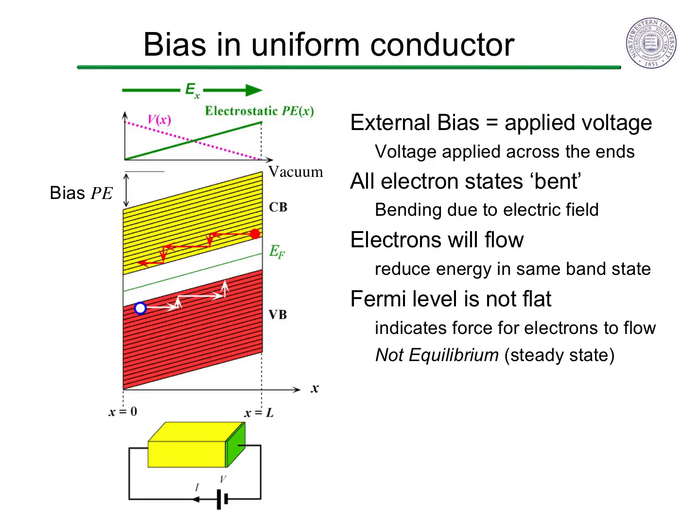In this non-equilibrium but steady state condition, the Fermi level follows the bias potential energy because it is the electrochemical potential of electrons, which includes the electric potential energy. A voltmeter measuring between the ends of the material will read this change in Fermi level as the electromotive force supplied by the bias voltage.